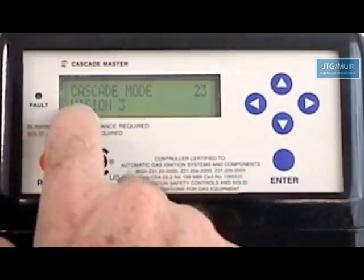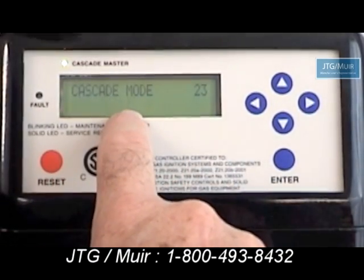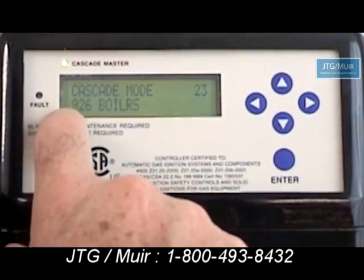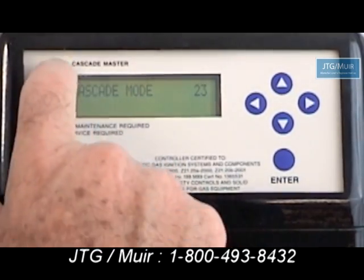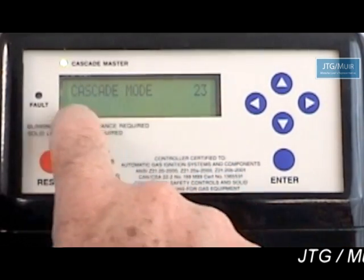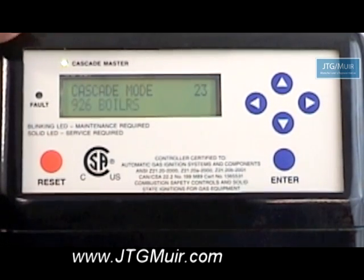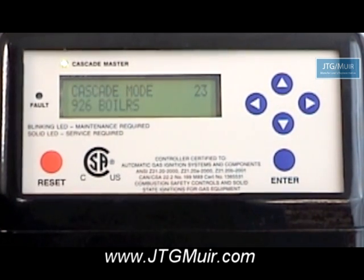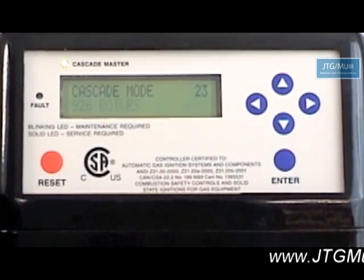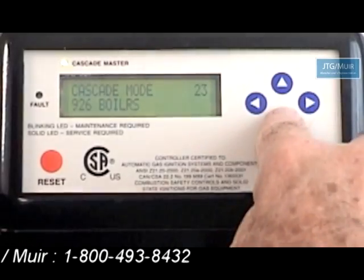If we choose to go with the Vision 926, which is the standard control board, this boiler, for instance, because I left default number 15 at 0, it's being considered to be the Cascade Master. And it says 926, and you'll notice the light is on. This boiler is going to be the one that's going to get the outdoor sensor connected to it, the Cascade sensor, and so on. Okay, I'm going to go back.